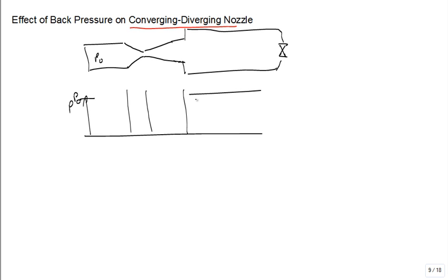So you start to drop it, drop it, drop it, and the flow, first of all, will simply have acceleration through the nozzle part, and then deceleration and pressure recovery in the subsonic diffuser until you're able to drop it such that you get choked flow in the throat. And at that point, you can continue to drop the back pressure. It'll start to get flow that will be faster through the section.